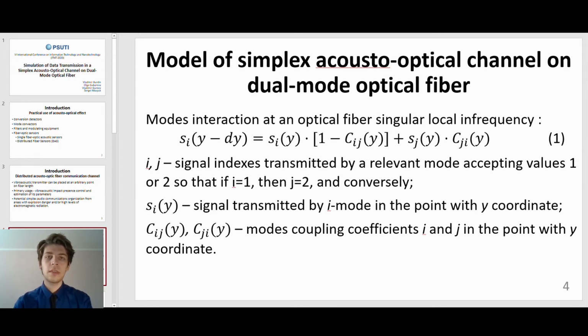In simulation, it is enough to consider two modes, supposing that the orthogonally polarized modes are degenerate. Each of the modes transmits a desired signal and crosstalk conditioned by the modes' interaction. As the desired signal is transmitted at low speed, we can ignore chromatic dispersion and optical fiber nonlinearity. We restrict ourselves to analysis of one optical fiber cable length, which averages 4 to 6 kilometers, that allows us to exclude junctural irregularities and to ignore losses. We assign indexes 1 and 2 respectively to mode settings and to the optical signals transmitted by them.